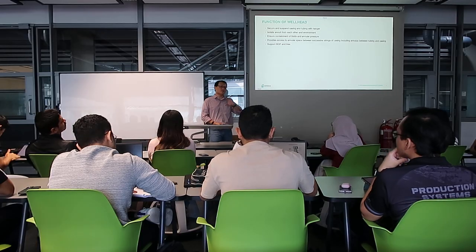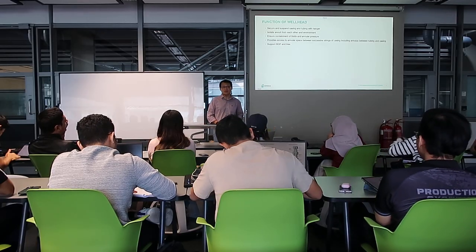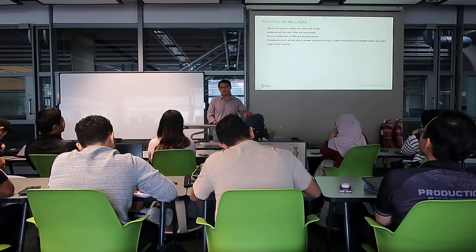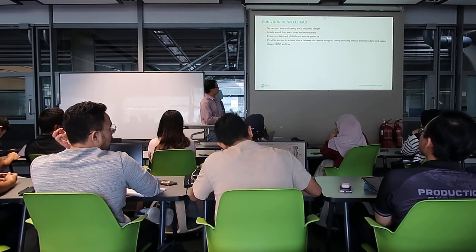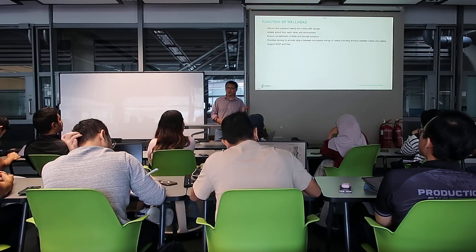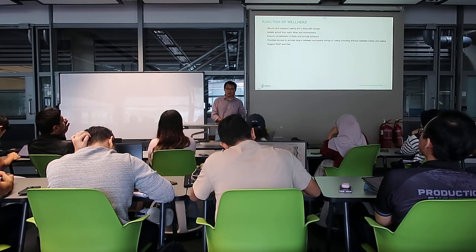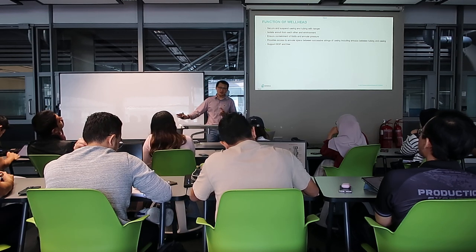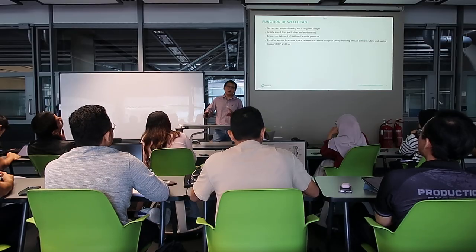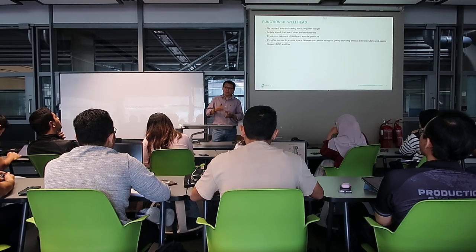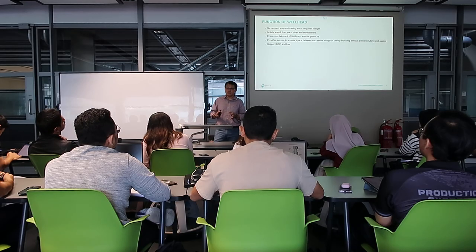And then it is quite driven by the simulations now. I think the simulation now is quite accurate as long as we put the input rightfully, right? So that's how the annulus space works, and then it's also to support both BOP and tree. So on top of the casing load, we also talk about the BOP weight, because every single well is freestanding. There is no load onto the platform. The whole well's architecture will really loop to the first string, which is the conductor.